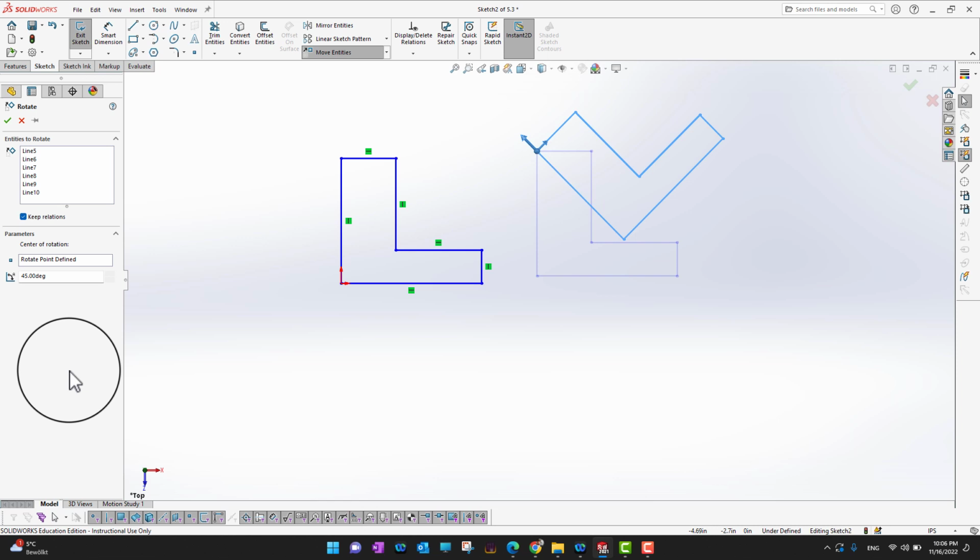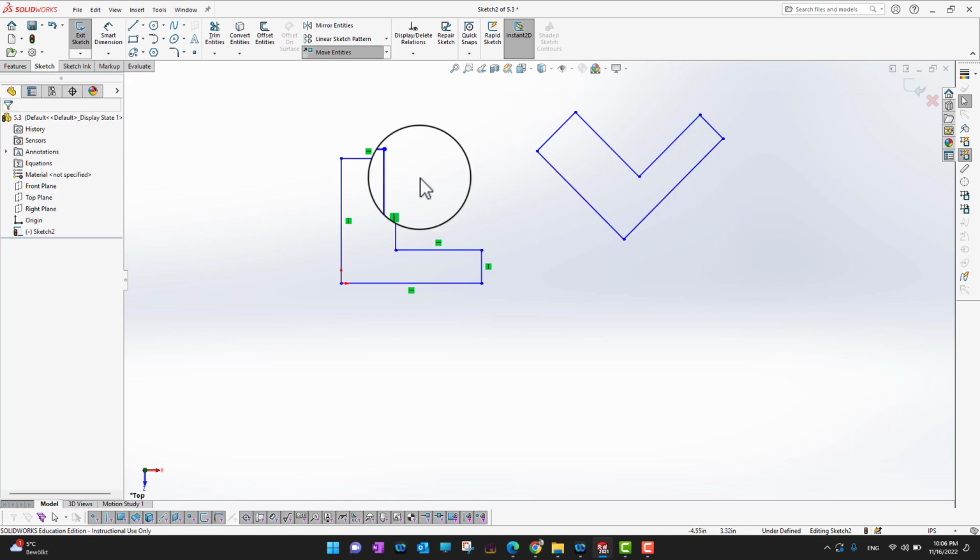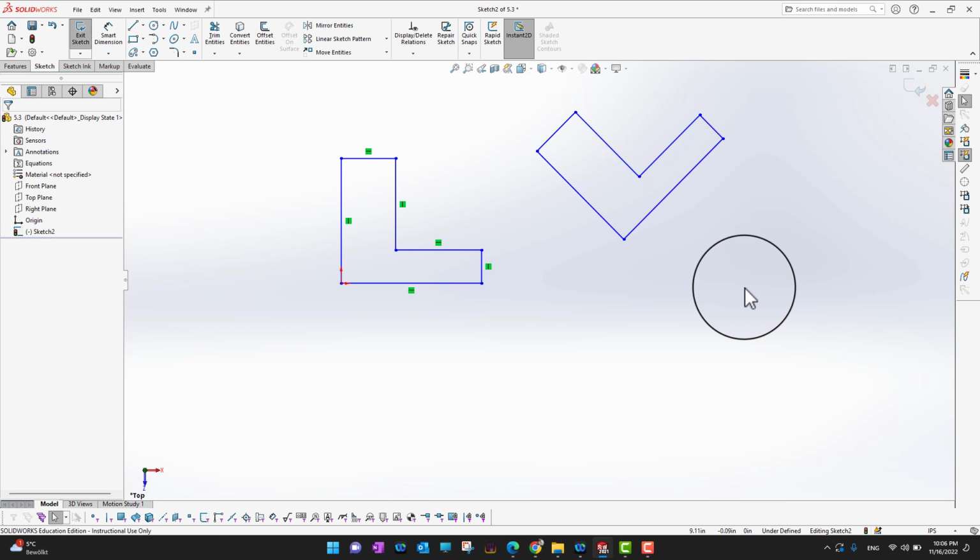it's going to rotate. Look, right now in this sketch there is a relation between the lines. This is a horizontal relation, this is a perpendicular line, perpendicular, horizontal, horizontal. Because everything is rotated, this is not horizontal or perpendicular anymore. But if you add a relation between two lines, if both are going to move, the relation will always be there.